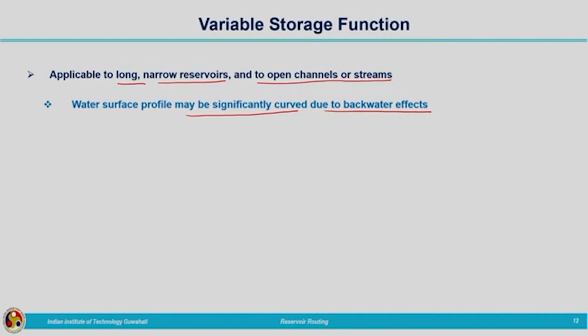If the length of the upstream reach is very long, as in a channel or a reservoir itself, there will be effects of backwater flow. Because of that, the water surface cannot be assumed as level or horizontal. It can be represented by a curved water surface profile.